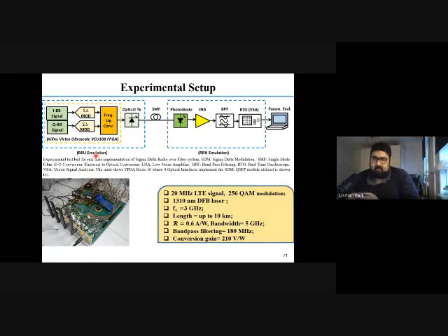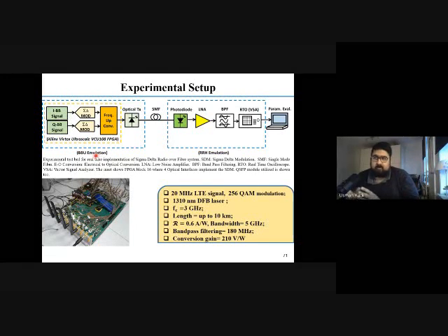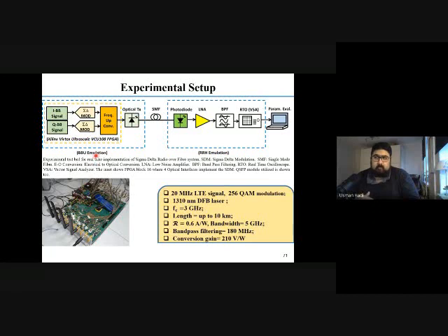So we had an understanding of FPGA. So we implemented the standalone frequency up-conversion, sigma delta modulation, and IQ signal baseband generation on this part, and then prototyped it with all the other equipment. And that was done for 4 channels, because the VCU108 allows you to have 4 channels of transmission at a single time. So that is still very good.